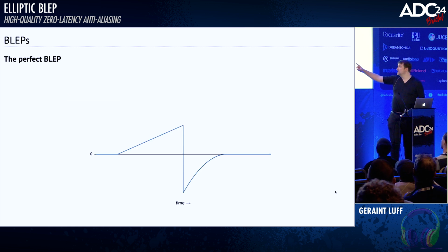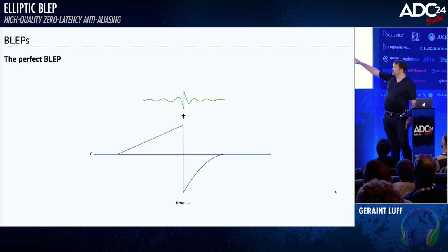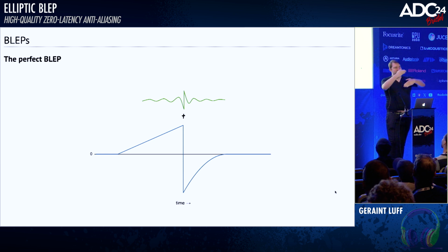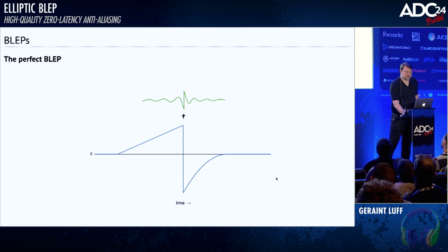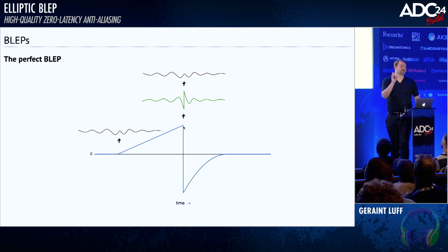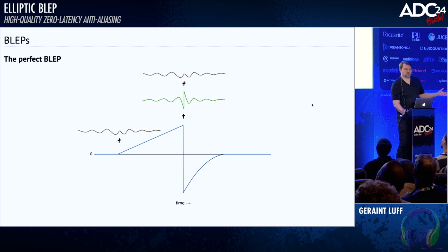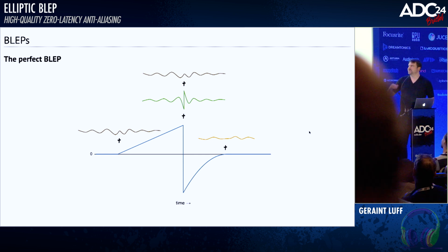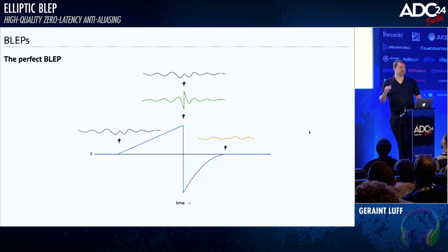So you've got your polynomial waveform here, and where you've got this big discontinuity, you take your aliasing cancellation residue and you just add it in, centered on that point and scaled so that it matches. But we've also, on the left here, got this sudden change in gradient. And actually, we've got a sudden change in gradient at the same time as this discontinuity. So we have to add in that as well if we really want to get rid of the aliasing. And then there's higher orders, and it can go as detailed as you want. And they all have funny names. Given that this is an infinite impulse response one, I did not call this technique BLERP, but I considered it.